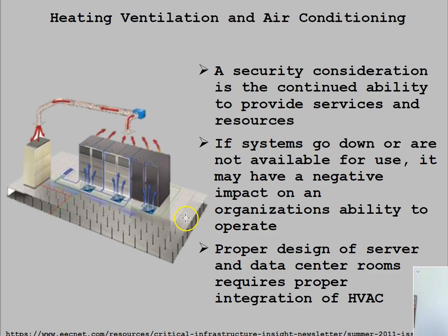And specifically underneath it here, we have this thing called the plenum floor. Plenum, for anybody that's concerned about spelling, plenum floor or plenum space. Usually you'll put photoelectric sensors in the plenum floor that are kind of like the garage door openers, how one side has a laser and then the other side has an eye, and if, let's say, smoke comes in between them, then that would alert somebody that there's a problem in the plenum floor underneath there. But usually those are false floors that you run the network cables underneath the ground, and usually they're no more than 8 to 12 inches.